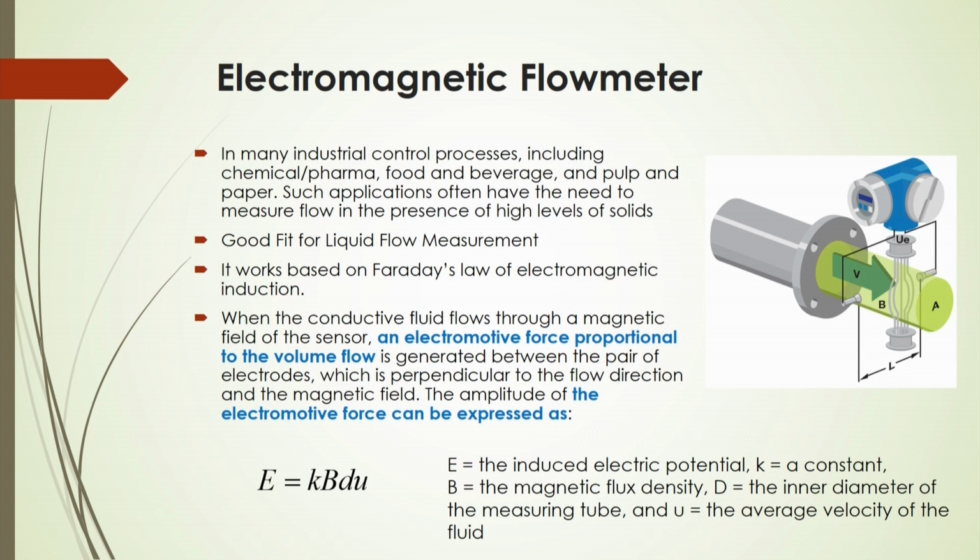Then of course, you cannot measure this flow with a rotameter or venturimeter or orifice meter, it is very difficult. So, in that case a special flow meter or device can be used. To measure this type of flow rate, you have to use the electromagnetic flow meter. It works very well to calculate the flow rate for this slurry type of flow.